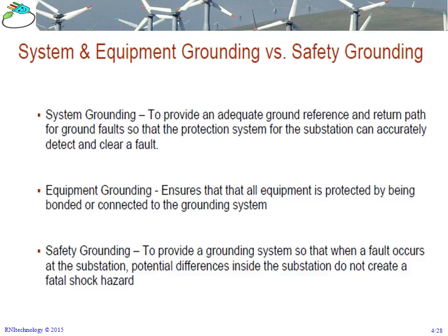When I say detecting the fault, this fault detection comes through appropriate microprocessor relays or electromechanical relays if you have an old system. And the way of clearing the fault comes through a protective device, whether you have a fuse or a circuit breaker. So system grounding can be an ungrounded system, which is the old way, or solidly grounded, which is the minimum requirement, or you can have high resistance or low resistance grounding, or reactance grounding.